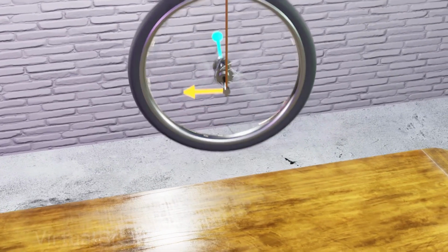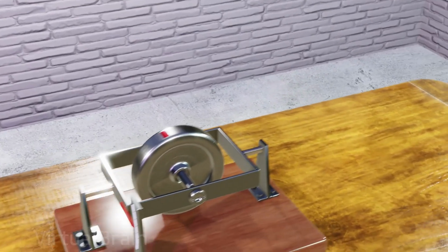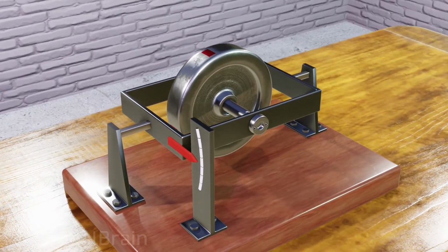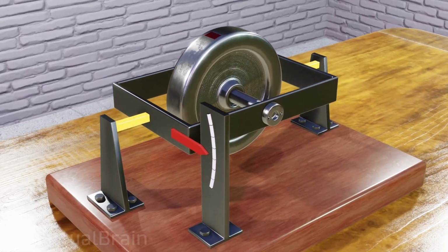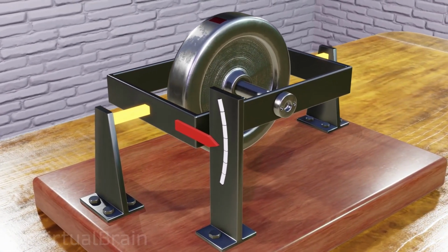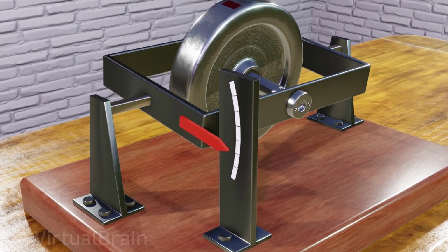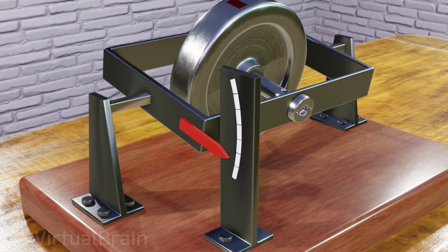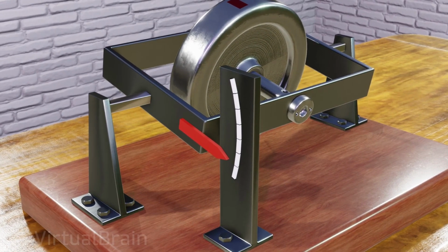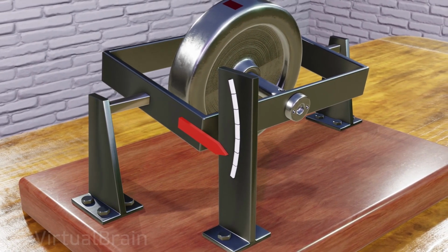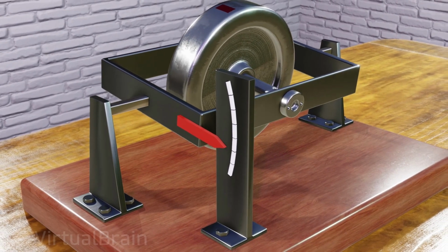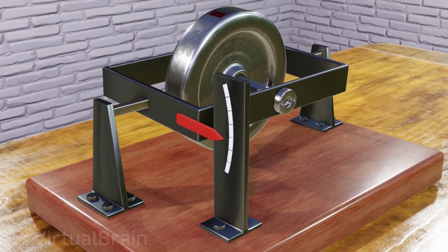More specifically, we can have a system like this with a rotating disk at the center, which in turn will be suspended by torsion bars. These will allow the suspension supporting the disk to rotate, but will also impose a resistance that will increase proportionally to the torque, which means they allow us to use the angle of torsion to calculate the applied torque, similar to how springs allow us to use elongation to calculate the applied force.